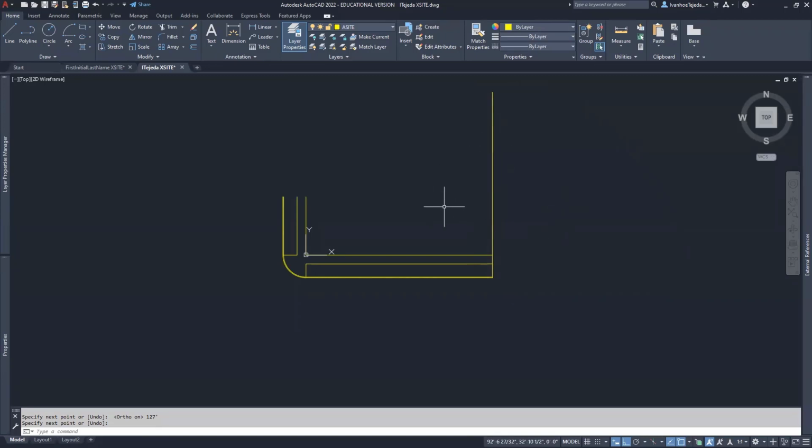And now what I'm going to do is offset. So I type O, enter, a distance of 15 feet, enter. And I'd like to take this line over in that direction and then enter to terminate the command. And this represents the alley. I'm looking at the drawing and I can see that it's a matter of simply mirroring some information over to the other side. But before I do that, I'm going to extend my lines over here higher up.